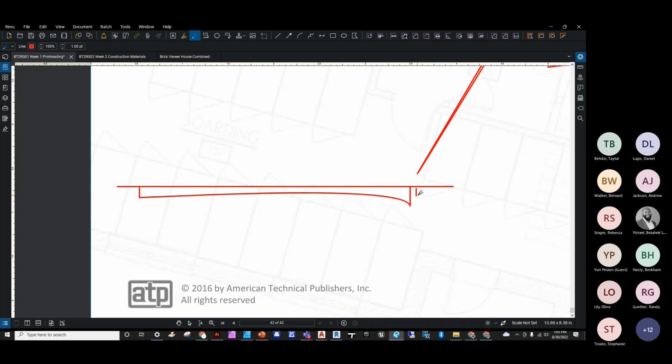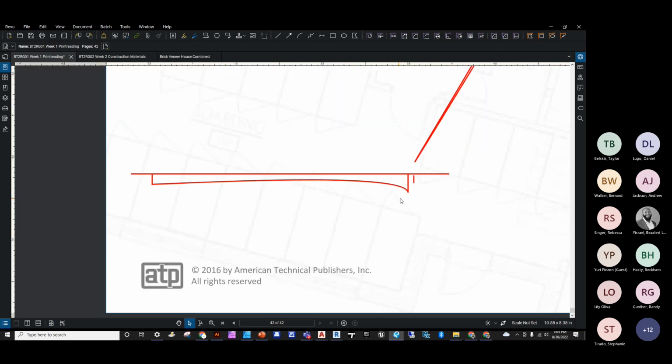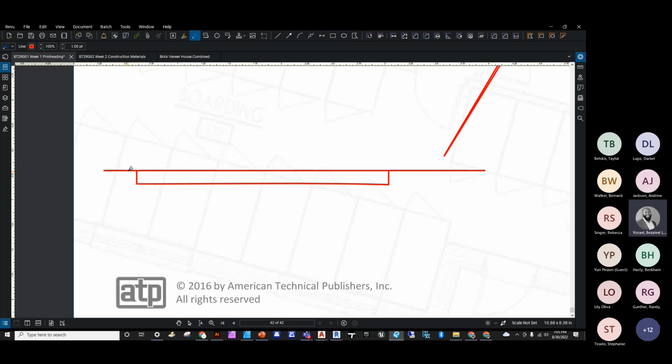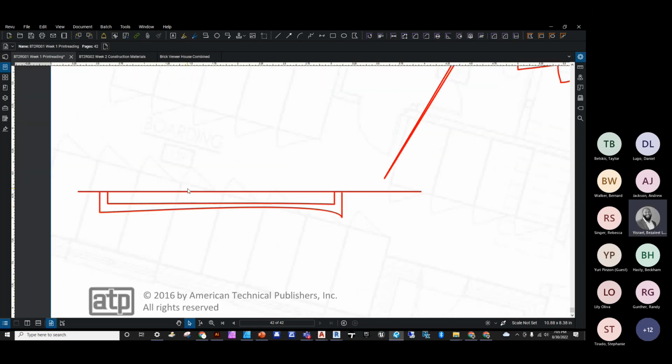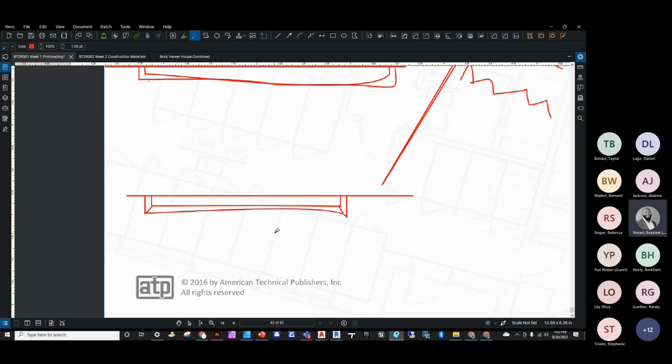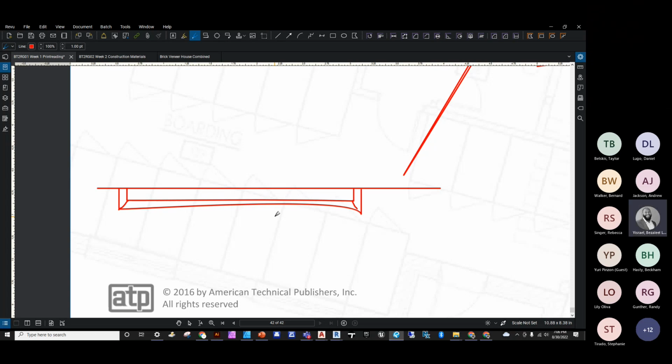So while you're drawing that, I've got an early 1900s, turn of the century house, and the handrail is just this long rod. So it's against code now. Correct. And you'll run into a case where in those instances, since it's so old, they'll say, okay, you're fine. It's grandfathered in. We're not going to make you change that. Typically you won't see them make you change that, right? But in cases where you want to do a remodel, and especially if it's an application where you're opening up to the public to stay in, they'll make you adjust or modify that so it's up to code.